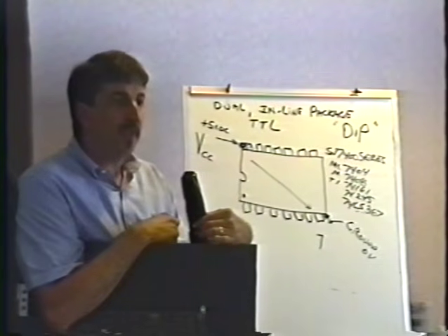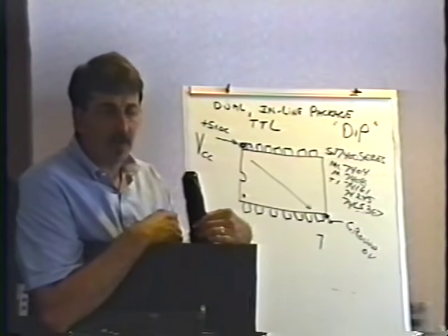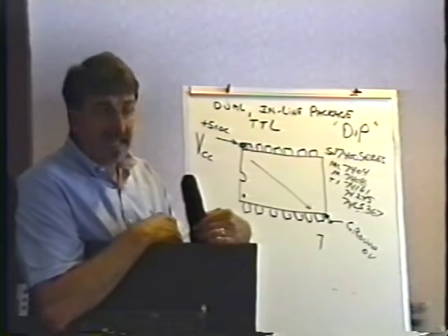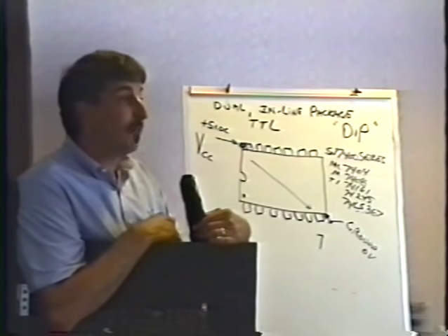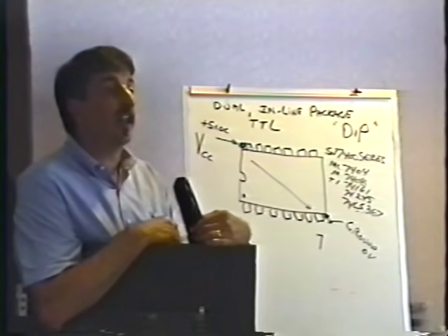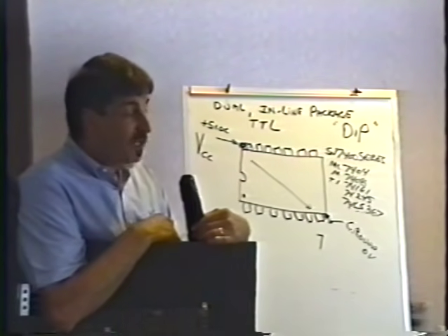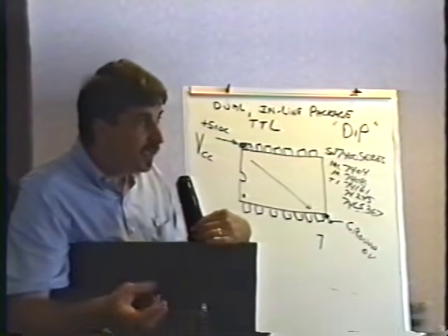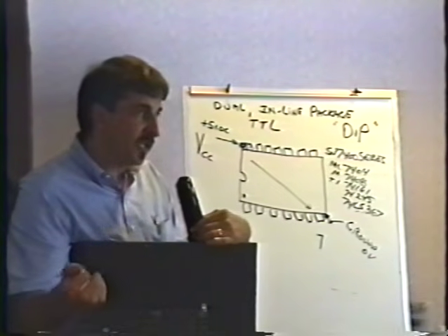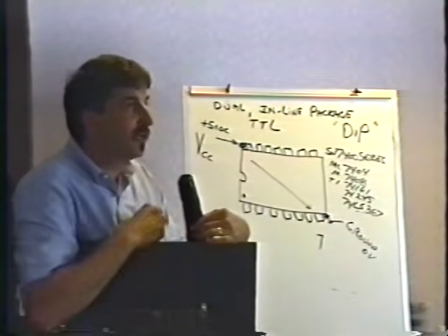When you measure it with your meter, it's 5.1 or whatever. But you have, I guess the best way to describe it is as a hidden power supply problem that your meter cannot locate for you. Sometimes power supplies put out a huge amount of electrical noise that your meter just doesn't see. An oscilloscope would see it, but your meter doesn't.